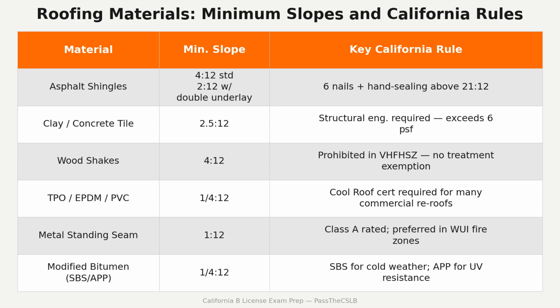One fastener detail worth having precisely. The nail must penetrate a minimum of 3/4 of an inch into the roof sheathing. Standard oriented strand board is 15/32 of an inch thick, which is less than 3/4 of an inch. When sheathing is thinner than 3/4 of an inch, the code requires the nail to go completely through. That is a precision distinction.